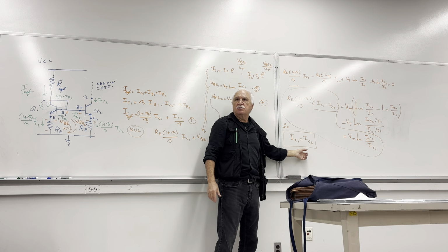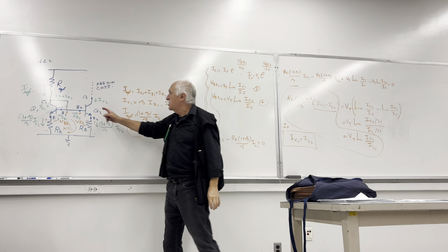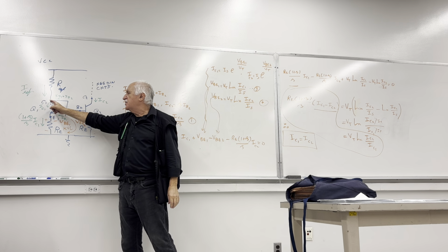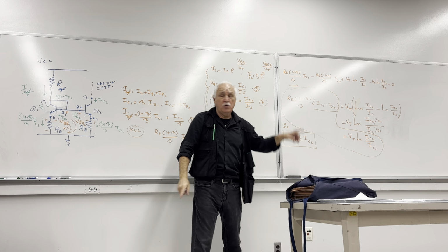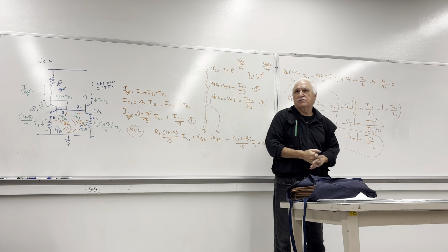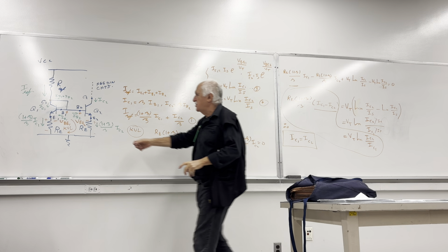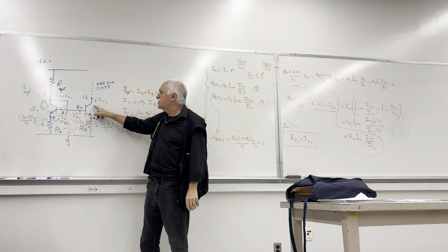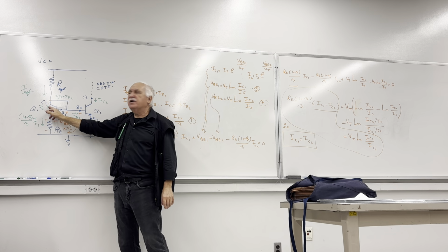So we've got this conclusion here: that IC2, the collector current generated in here, is a replica of the collector current in that transistor, although we have two resistors in the emitter. That's what it proves. Although you have two resistors here, just like before, the collector current here is a copy of the collector current over there.